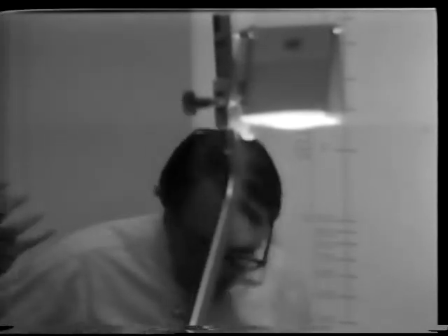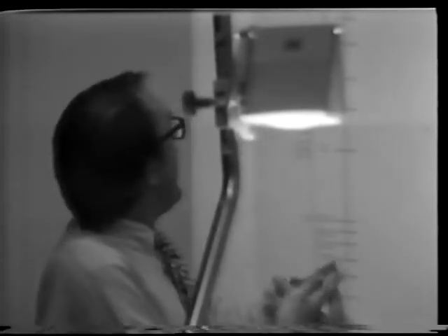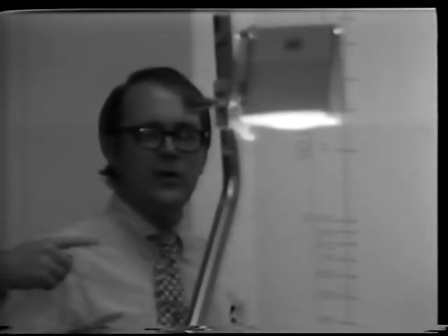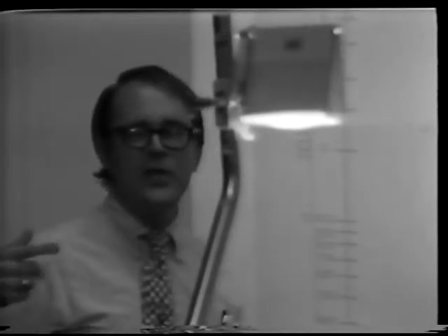If you look at our machines, the 5 had a MAR, memory address, and memory buffer register, which you need for memory, and it had one other register that could do addition, an accumulator, and then 2 other bits, an interrupt bit and a run bit. And then the link.